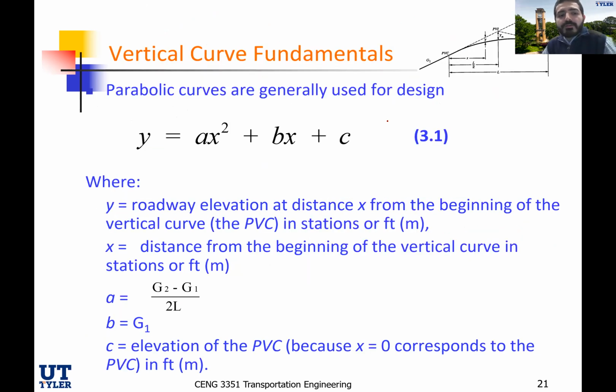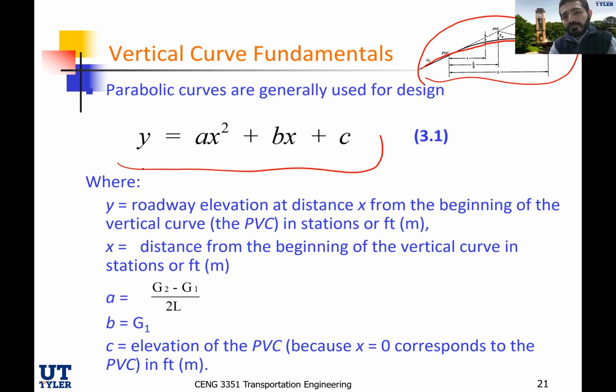All right, let's get going with some equations. Those are equations that we need to understand, and where we are getting the final equations that we're going to use in the design. For a vertical curve, as you see in the picture on the top here, if you think about it, this curvature is actually following a parabolic equation, like what we had in mathematics, not even Calc 1, it's before Calc 1. Y is equal to ax squared plus bx plus c. That's as simple as that.